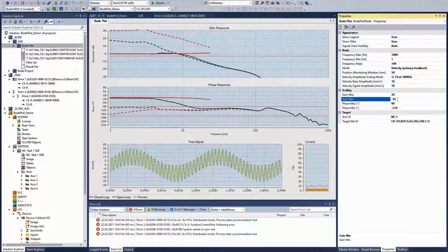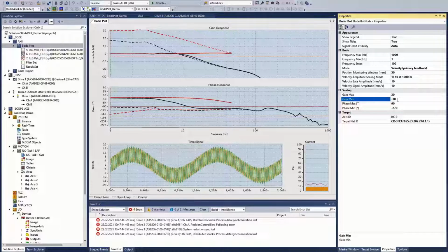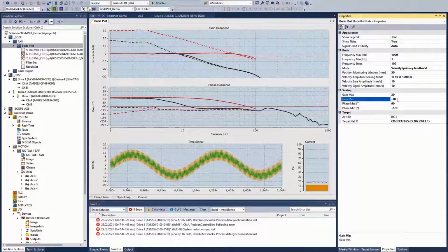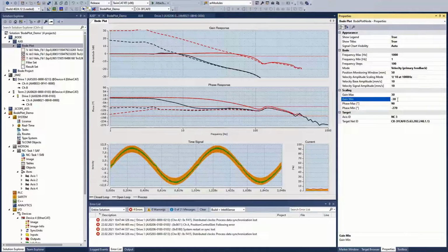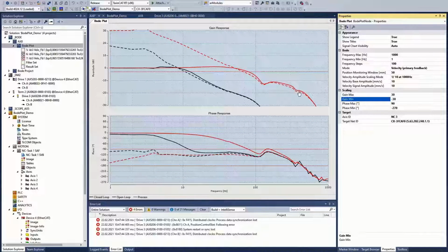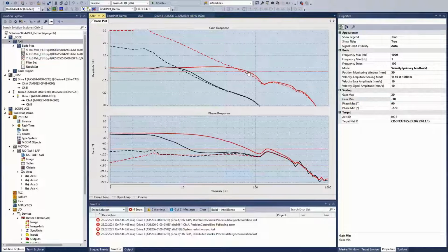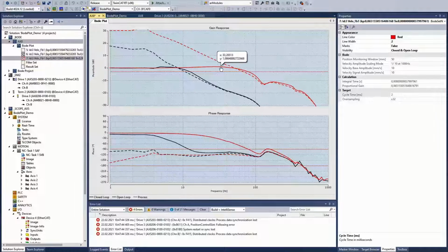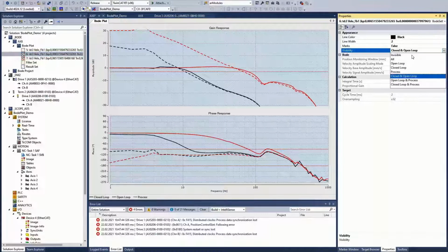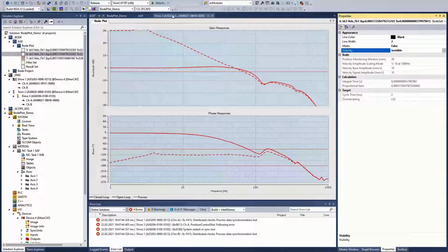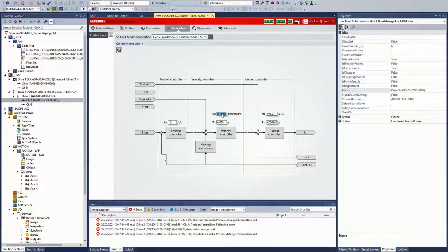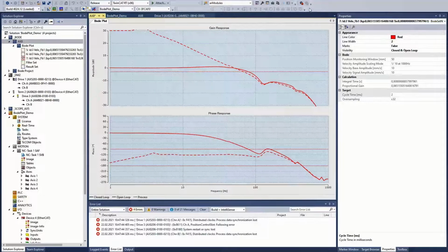You see the closed loop is still on the 0 dB line. Now it's going down, but we are in a range of maybe 80 Hertz. And at the same time, there is no resonance issue anymore. So, good improvement. Yeah, 80 Hertz, peaking 1 dB, both is nice, acceptable. Then we can maybe go ahead, increase the gain one more time, and do the next plot.